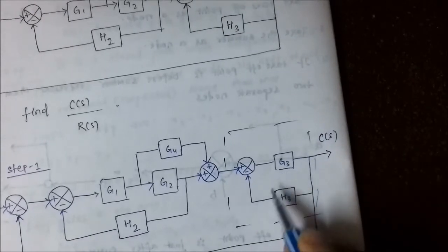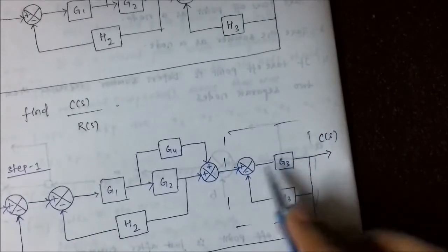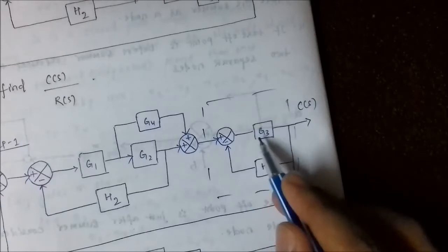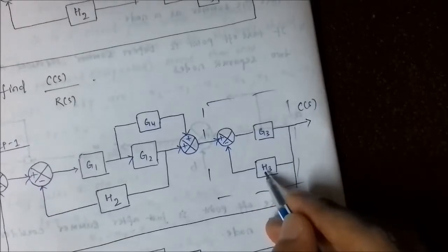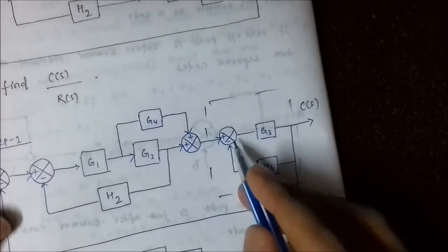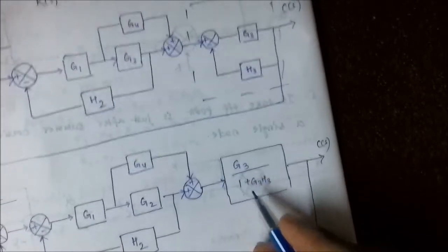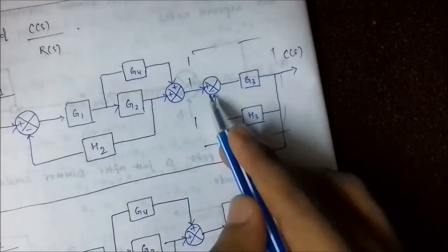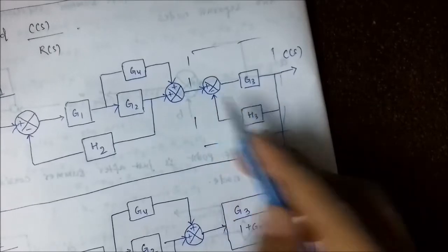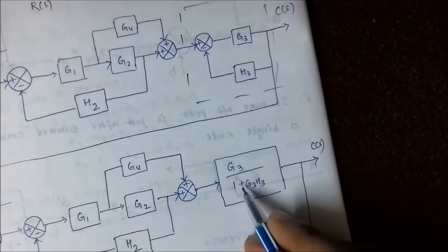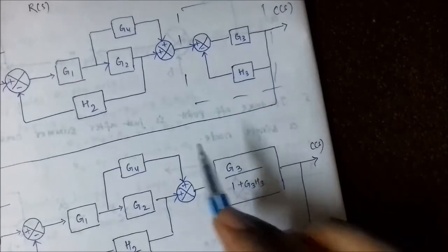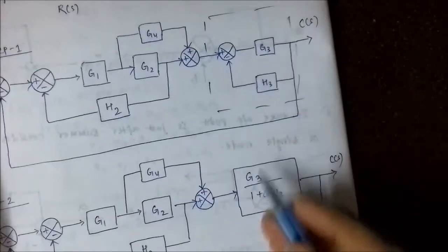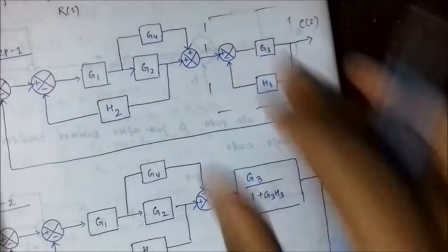This is a simple feedback control system. There is a feedback connection from the output to the input. This is the forward path transfer function, this is the reverse feedback transfer function. So what we have done here: G by 1 plus GH. Remember, forward path, reverse path. Here it is negative, the negative signal, so here it is the positive sign in the denominator. The block diagram reduction rule which we studied, when we have a feedback connection, we apply this rule. So we have solved this portion.